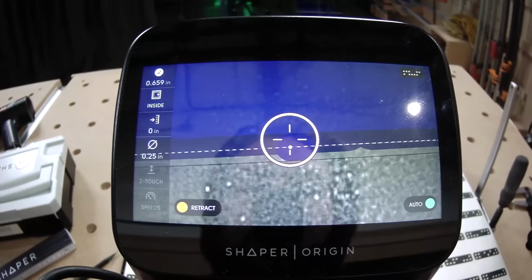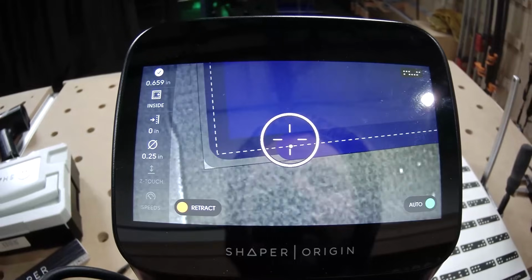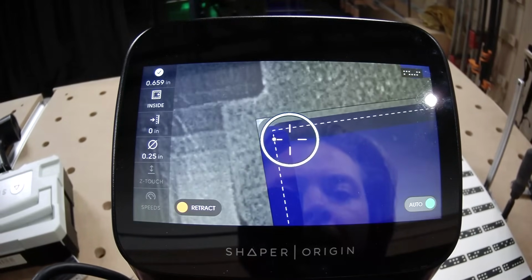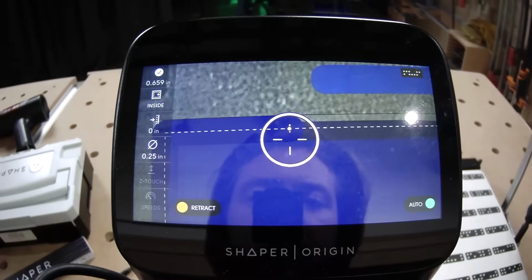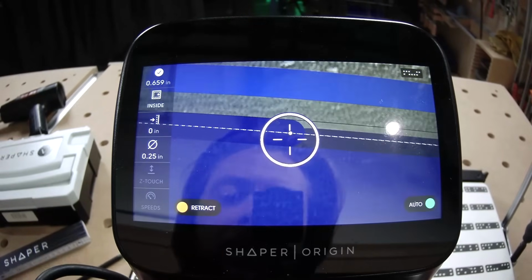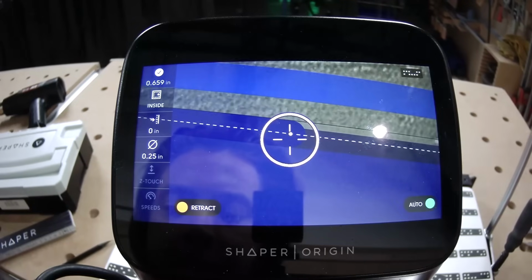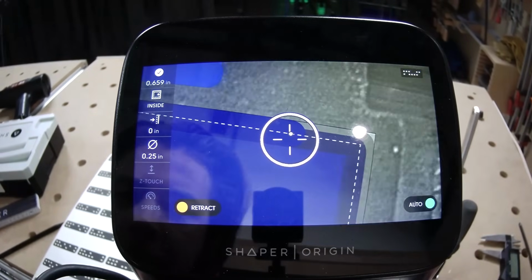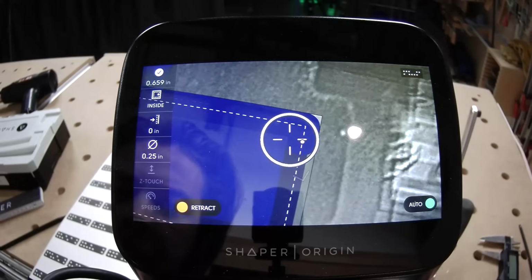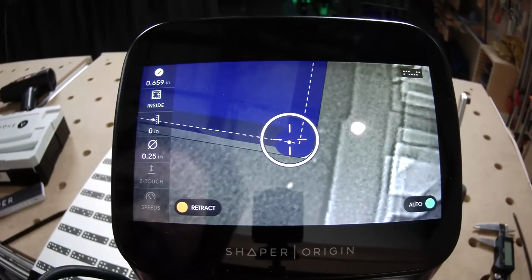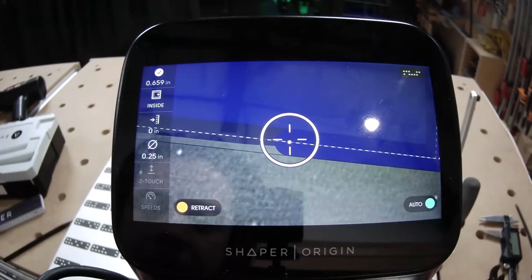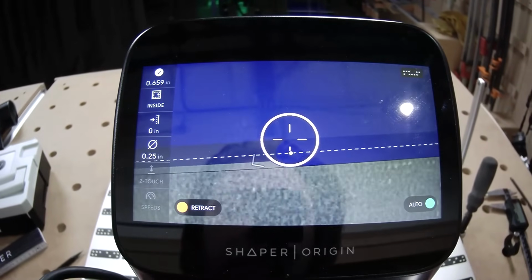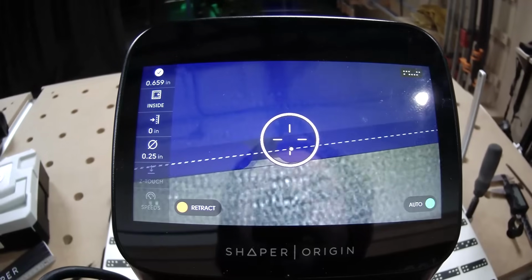And now that we're on that inside cut, you see that dotted line reappear. That dotted line is going to give us a very clean, smooth finish at the edge of the pocket for this ruler. And as Jake's following along, you can see he's floating kind of toward and away from that dotted line, but the dot, which represents the center of the spindle, which represents your router bit, is staying locked to that dotted line, keeping him right on the path.